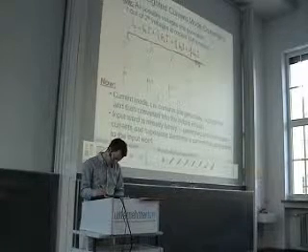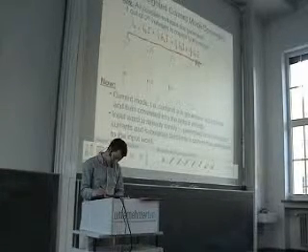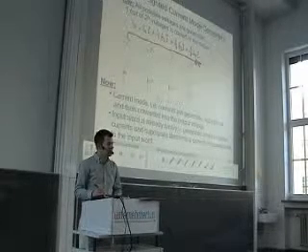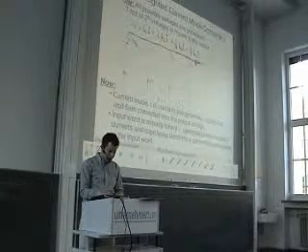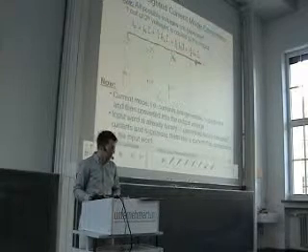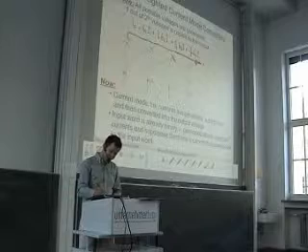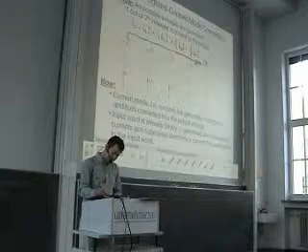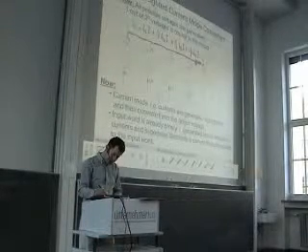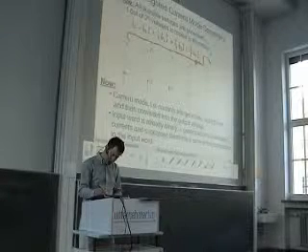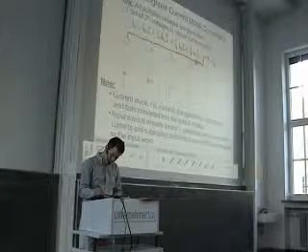So you might say, well, we want a DAC that generates a voltage, not a current. Here we have a current that represents the input word, and we can convert this current into a voltage by forcing this current through the feedback resistance of this op-amp.